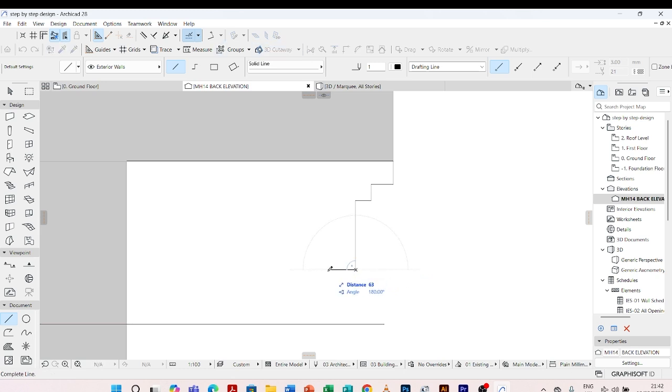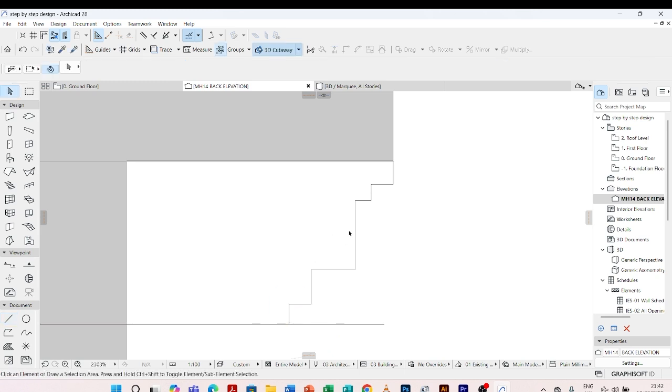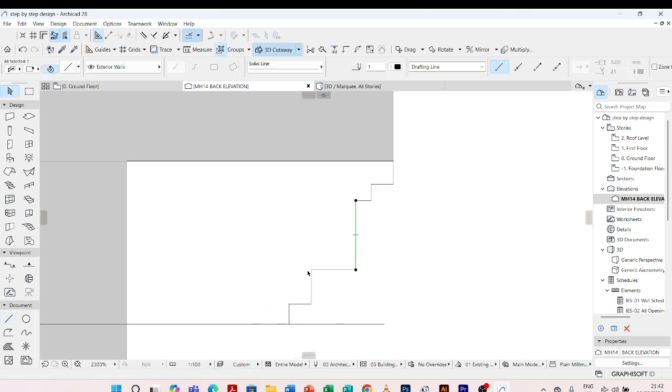So I'll move again back by 100, and I'll drop down by 75. I'm just sketching my profile. You can also sketch yours as well. Then I can move inside by 50. Then I'll drop down and finish from there. I'll need a curve.